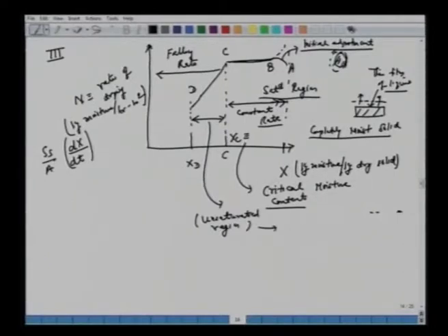Now you start seeing the dry patches. Some surface has been dried up and on some surface there is still a thin film of liquid. You recall also that if you measure this in kg per meter square of wet area per second, then whether you are in this region or in this region, the rate should be the same, which is the same as the rate of typical evaporation. Since we are defining it to be consistent with the total area, there is a decrease in this.